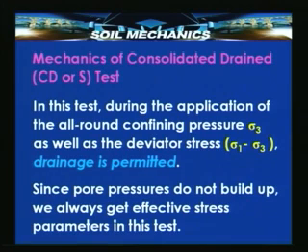That is why this permits total consolidation to take place during the first stage of loading and drainage to take place during the second stage of loading, and that is why it is called consolidated drained test. This implies that the loading is slow enough to allow water to expel and not build any pore pressure.